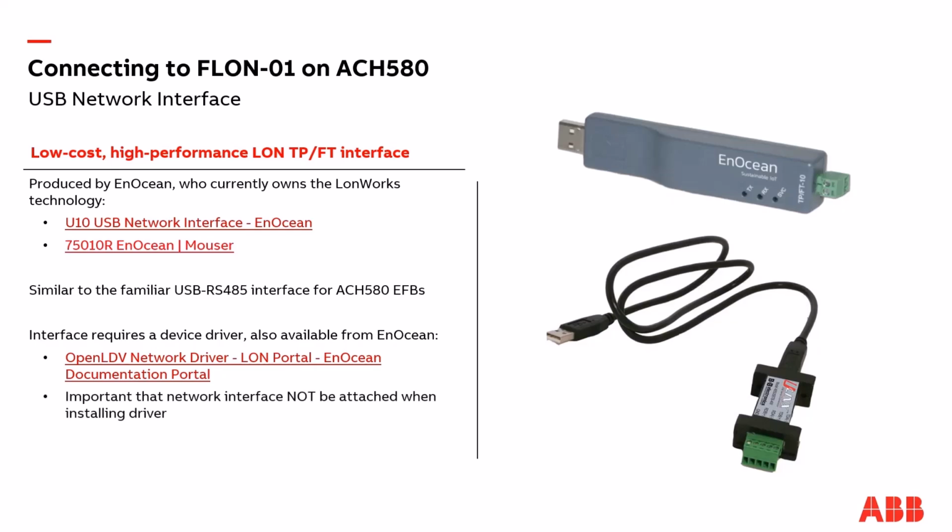But I will make one comment, and that is it's really important that the network interface not be connected to the host PC when you're installing the device driver. If it is, the installation is likely going to hang up and then need to be aborted. Once the driver is installed, you'll be able to see the attached drivers, and these are visible in the host PC's control panel, which I'll demonstrate on the next slide.